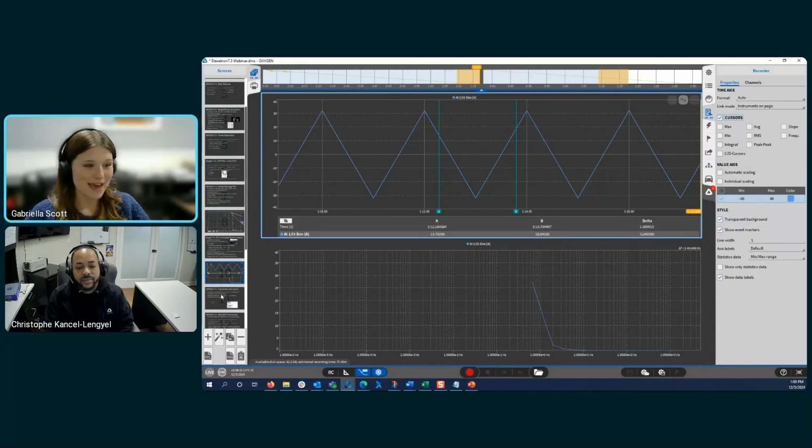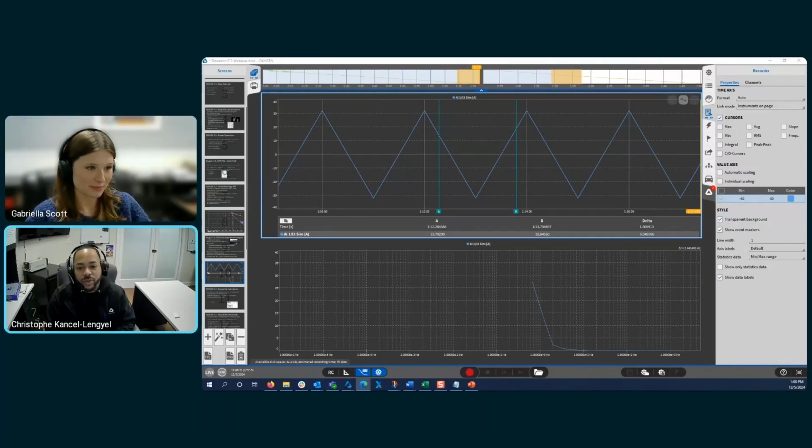Okay, great. Backtracking really quickly, we did get a question. What is the input for the GPS plot? Yeah, so for the GPS plot, you're going to need latitude for channel 1, longitude for channel 2, a heading, and then for the GPS plot, it's going to be a fourth channel, so you can have velocity, elevation, pretty much whatever you're trying to measure and wanting to see a change over time.